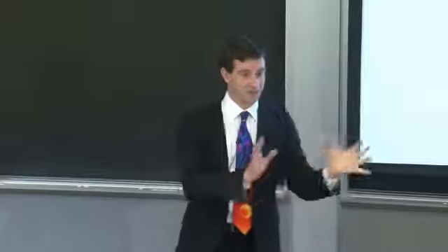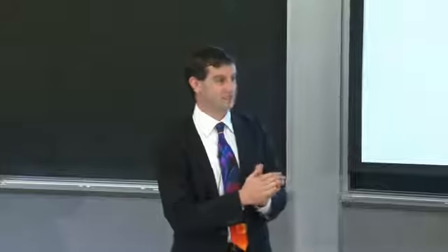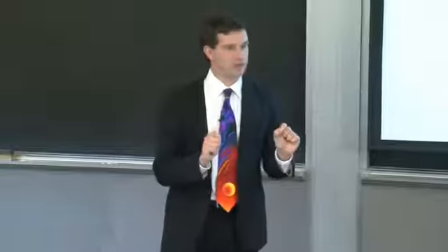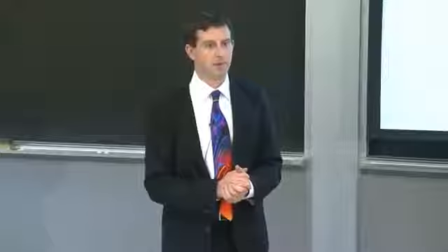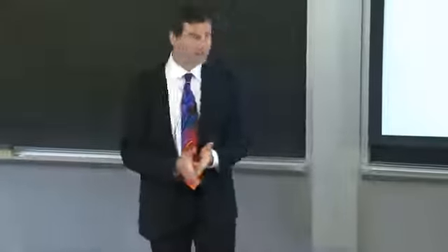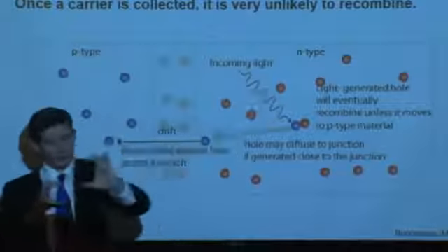Now, those length scales, which we were talking about hundreds of microns, maybe even 1,000 microns, compare that now to 10 nanometer diffusion length, say for an exciton in a polymer blend material. Then you have to reconsider your device architecture, how you're going to actually collect them. So this is a very generic picture, which could easily be substituted instead of N-type, P-type. It could be easily substituted by, say, polymer 1 and polymer 2 that just have the right band alignment to separate charge. Then it gets a little more complicated as well.